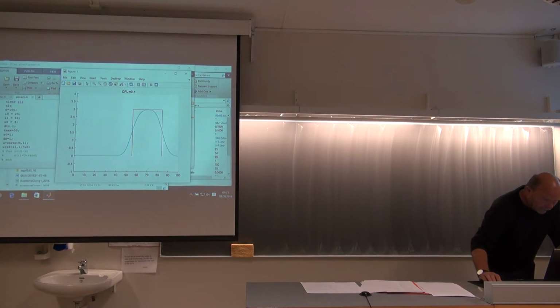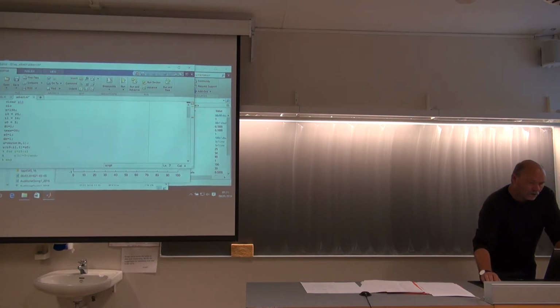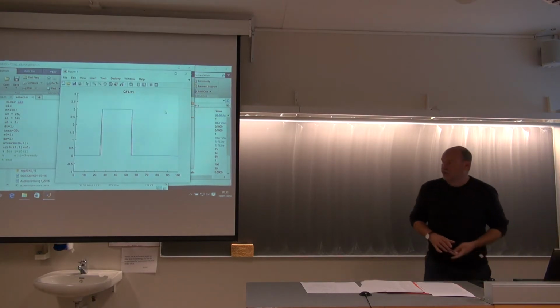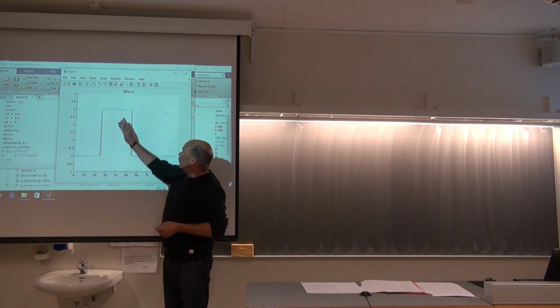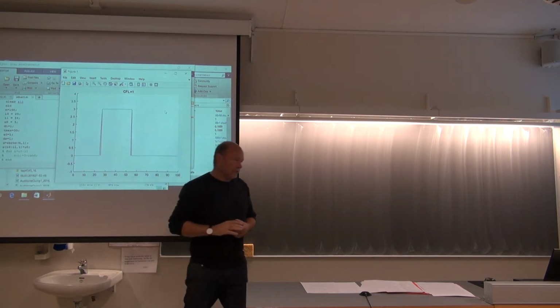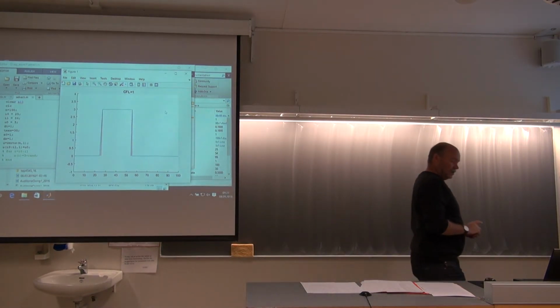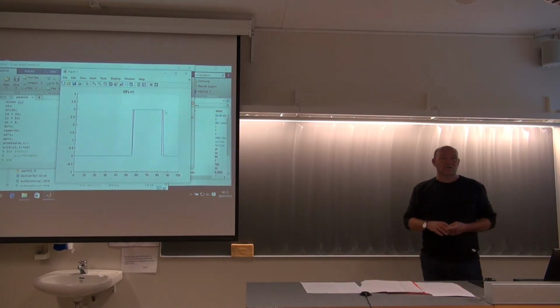Now we can just show the change for the first order upwind scheme. I have now pushed the time step all the way to the maximum. So now my CFL number equals 1. And finally, yes, you get the correct solution.